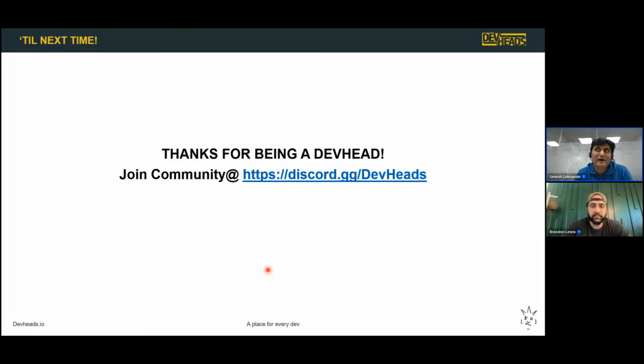And I think with these scenarios, like how these vendors are providing these libraries, let's say if you use STM32H7, you can have a TCP/IP stack with the ThreadX RTOS, right? I hope I'm right, the name ThreadX was bought by Microsoft, right? So that is the implementation off the shelf, but it doesn't have an implementation for FreeRTOS, right? But ThreadX is very popular and very stable. So you can do a lot of things, even if your requirement is very high throughput, low latency applications.